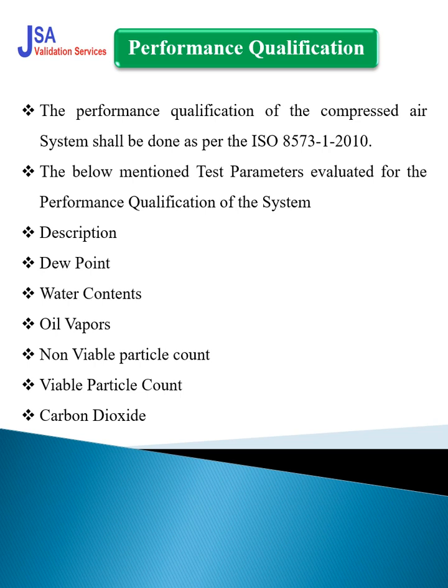So there is one basic guideline for the performance qualification or requalification of the compressed air system, that is ISO 8573 parts 1 to 10 published in 2010. And one more guideline that you can refer to for the performance qualification and commissioning of the compressed air system is the ISPE guideline for process gases. Okay, so basically